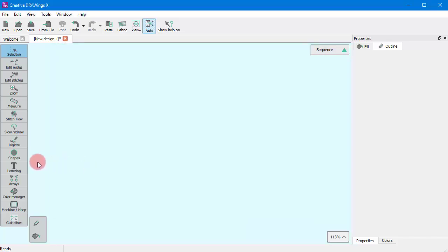When the tool is activated, left-click to draw points. Click once on the working area to start the starting node. Now a preview line appears from the starting point and follows the cursor. If you click once again, a line is added starting from the first defined point to the second. A new line begins from the second point. In this way, you can continue adding connecting lines.